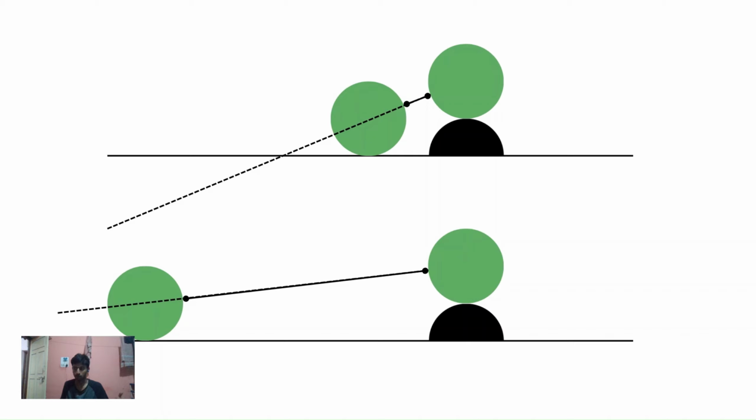Because of that, the rider sitting inside the car does not experience the obstruction even when the car is going over it. The total pitching motion is so minor that he just considers that the car is going on plain road, and that's how cars with longer wheelbases tend to be more comfortable.